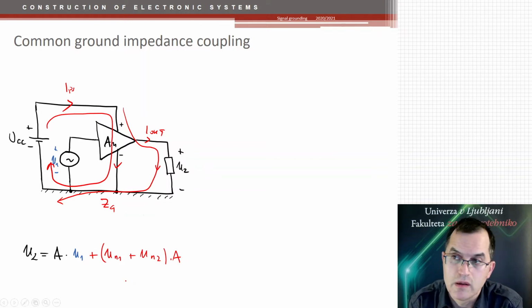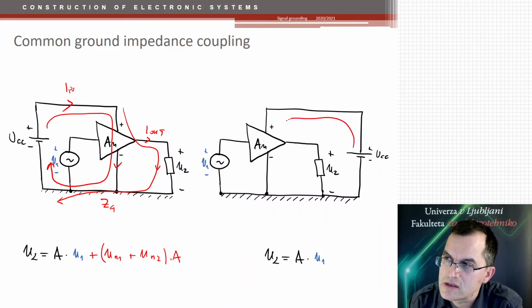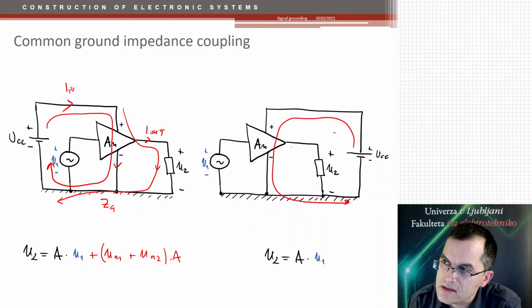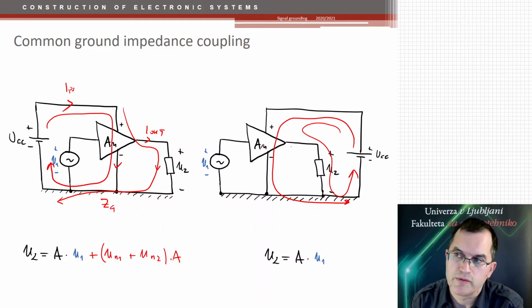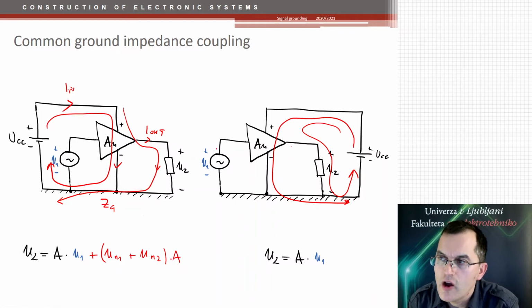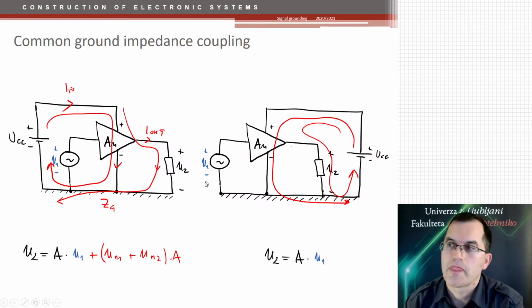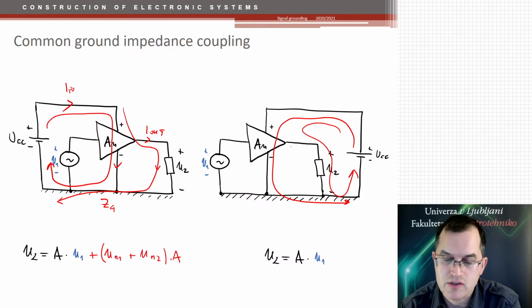So again, by careful placing and routing, we can actually get rid of most of that current or noise just by putting it in a way that it does not influence the input voltage. By placing the input sensitive part of your circuit away from the noisy part, including the power supply currents and all the rest, your output voltage is then free of these noisy signals. So careful routing, including using the ground planes as low impedance connections, will minimize all the noise coupling of the ground.